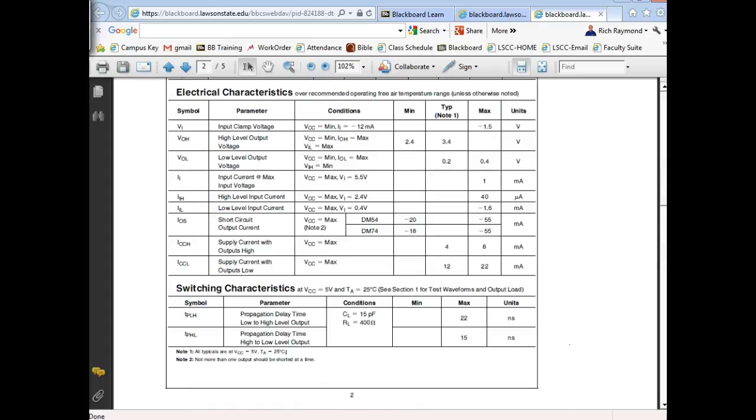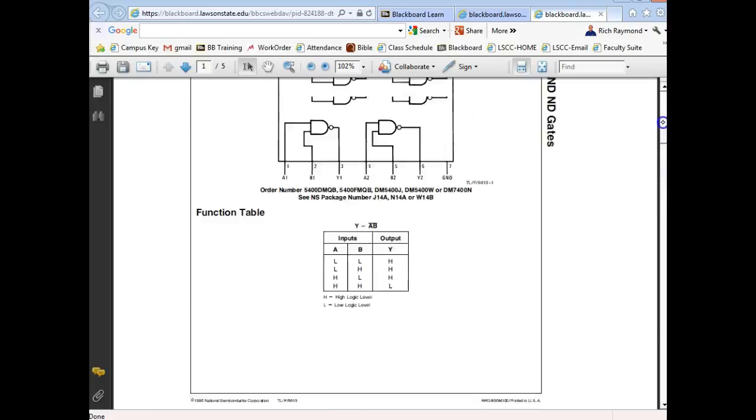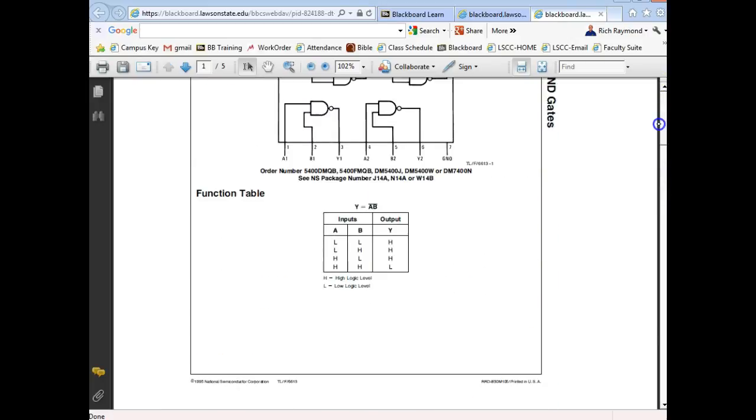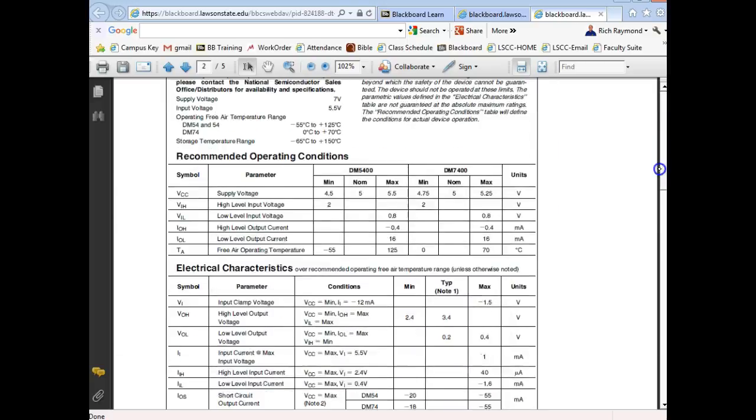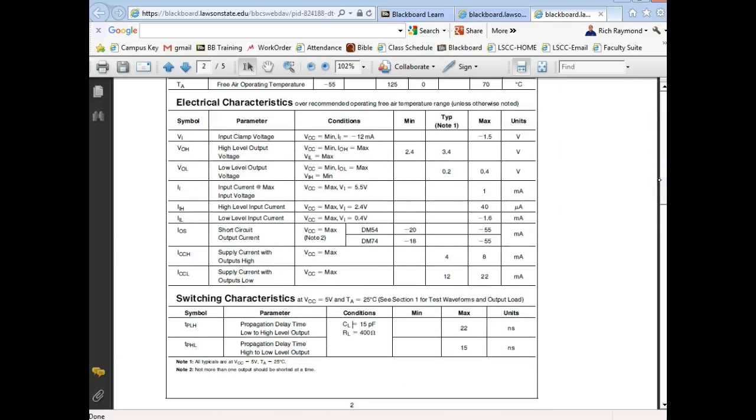So this guy here has a propagation delay of, here's propagation delay right here, of 22. It says 15 and 22, but if you go from a low to a high, right? You understand? Yeah, so if I was trying to time, I would use 22 nanoseconds for the output to respond to the input, and that's guaranteed. All right, understand? When I go back over here, this was the standard series. Propagation delay is how long it takes for the signal to get through the gate itself. Okay, y'all understand that?